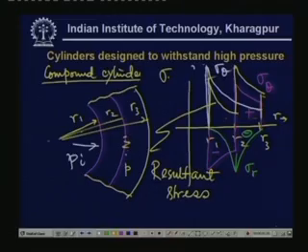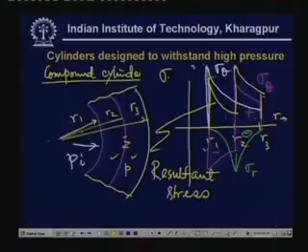We have designated this to be P. Now this was acting externally to the first cylinder and internally to the second cylinder, but what is the value of P? That is very important to know, because all this distribution will depend on the value of P, and this value of P exactly depends on the clearance between the 2 cylinders.